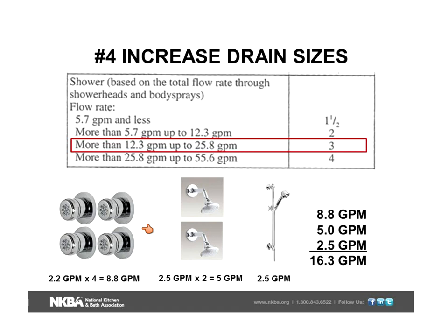We assume that the maximum water would be used, 2.5 by code. That gives us a total of 5 gallons per minute. We add to that a handheld that might be running at the same time, and we have a combined total then for all of the fittings in the shower at 16.3.